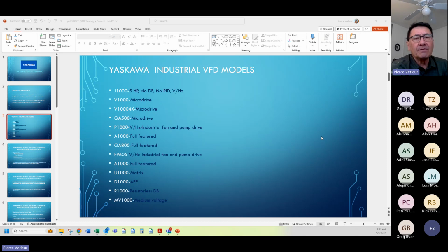Thank you very much, and it'll work very well. This is a constant torque drive. Just because we say it's a fan and pump drive doesn't mean it can't produce constant torque down to well below 1.5 hertz on a good, efficient, high-quality induction motor.